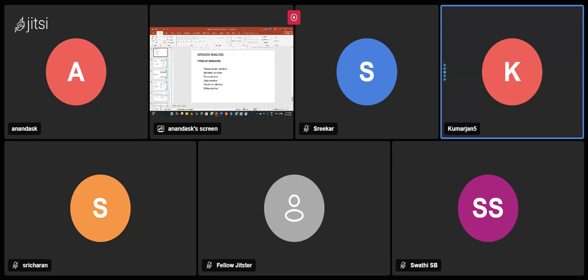If you take a look at the graph window, for instance, let us say one EVCU is giving wrong messages. When I press the brake button, the light is not glowing at the back red side of my light. So I try to see what the EVCU is sending with the help of the graph window. When the EVCU is sending the command, we have to check whether the brake system is acknowledging my command.